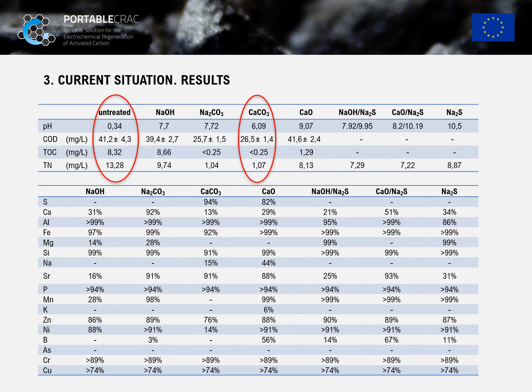For the removal of inorganic substances, the preferred treatment would be neutralization and precipitation. The final effluent generated after a neutralization with sodium hydroxide or calcium carbonate can be directly discharged into the environment, and the sludge generated can be disposed of in a landfill.